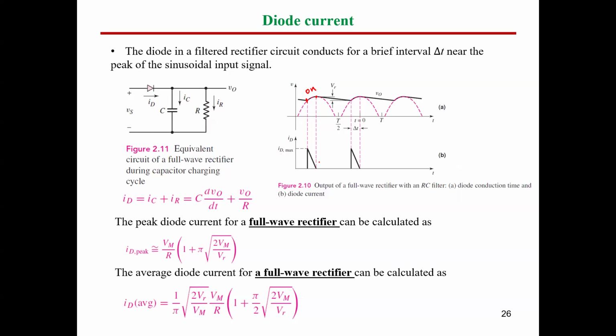So you will find this is the shape of the diode current. For sure, guys, the diode will be turned off once the diode current reaches 0. As you can see here, the diode current reaches 0 at the instant of turning off, and this was the current value at the starting. So this is the part of the current waveform we have during the diode turn on.